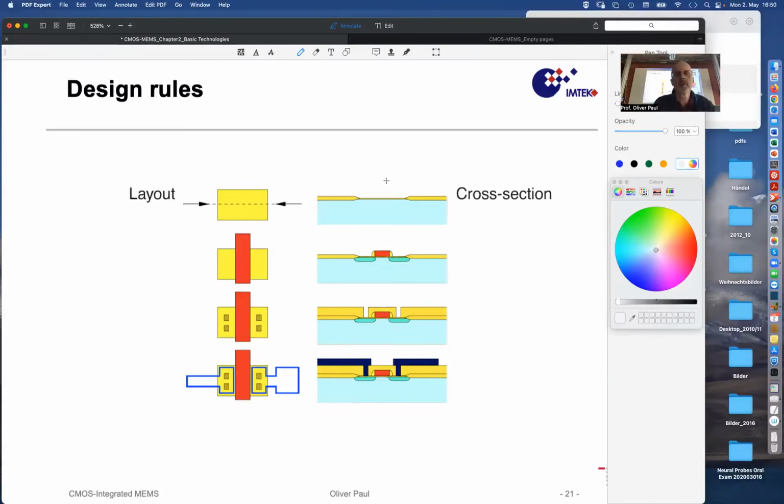So that in the back and in the front, there's also field oxide. There is a square surrounded by field oxide. In the middle, there's nothing. The active region is a square. And then after many steps, we have ended up with defining the polysilicon structure. So the polysilicon structure will be a line running over that active region, ending maybe slightly on the field oxide on this side and on the field oxide on this side to receive a contact, maybe here, to be contacted with metal later at this location, outside of the delicate transistor region.